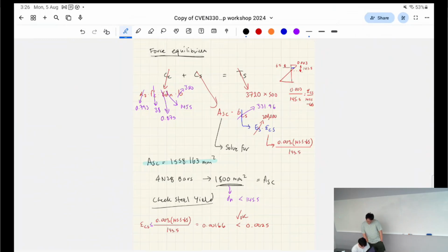so this is PQ, right? And you're saying all of these are uniformly dead load, WG, right? So how do I unlock that one? Basically, case 1 is only dead loads. So in this case, you just look at the uniformly distributed load. You ignore the point load completely. Case 2, 1.2G plus 1.5Q. So you still need to factor in this because that's a dead load. But now here's where you factor in that live load as well.